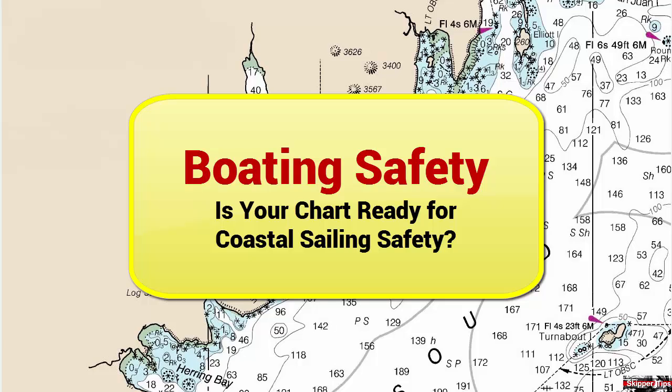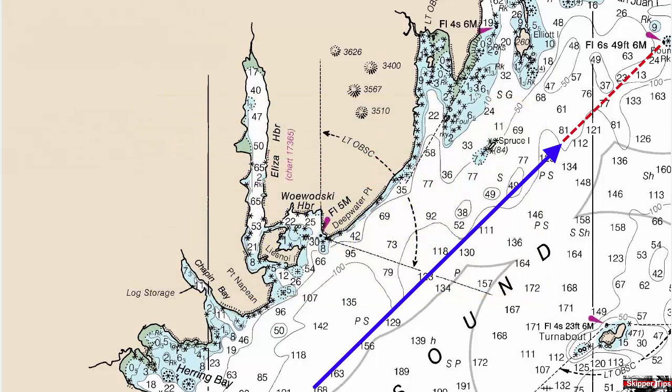In today's video tip, I'm going to show you some things I use to evaluate a nautical or electronic chart in piloting waters. Note here that we're going to be sailing on a track to the northeast. First thing you want to determine is the favored side of the sailing track. For evaluation, you would use wind direction, proximity of shoals, anchorage opportunities, traffic flow, and harbors of refuge.